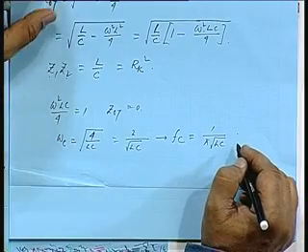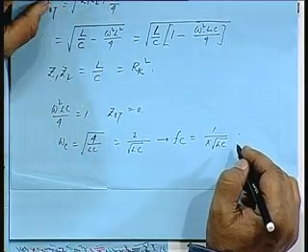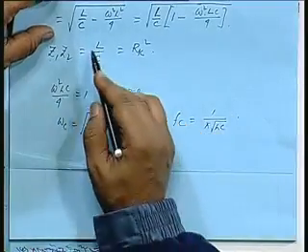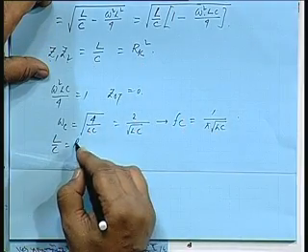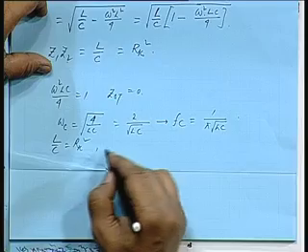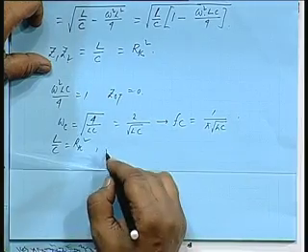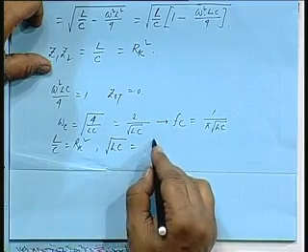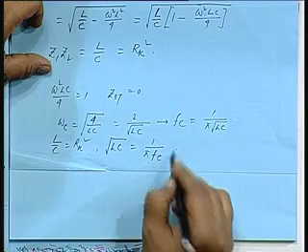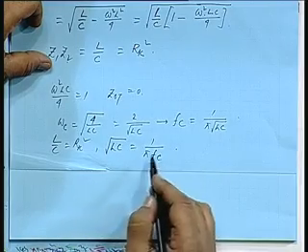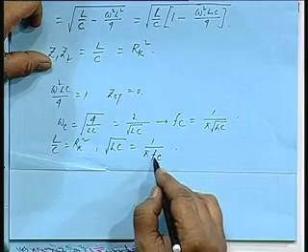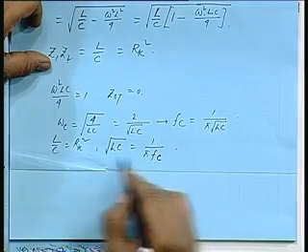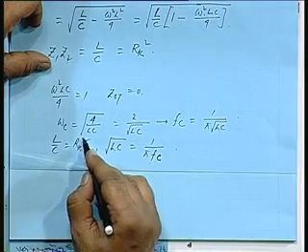We have got two equations. L by C is R k squared and root L C is 1 by pi f c. So, we may be given a specification in terms of the cutoff frequency f c and the constant R k.